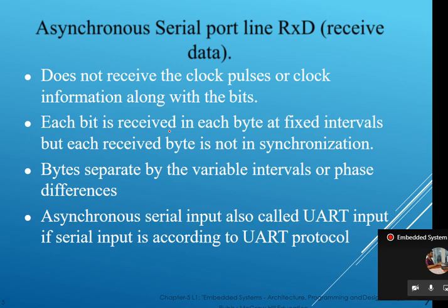So here we can't tell the speed of operation using bits per second. Why? Because I'm introducing some delay, and I'm not sending only the data, I'm sending the data along with the start bit, stop bit, parity bit, everything. So we can't explain it in terms of speed, like Mbps or bits per second. So here they will represent it using the baud rate.